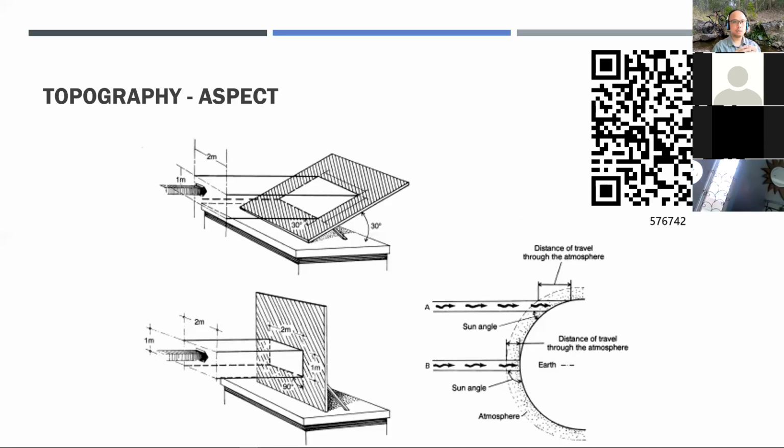As with other physical attributes, the importance of a slope's aspect depends partly on the proposed use of the site. At higher northern latitudes, for example, south-facing slopes are better suited for siting buildings that will incorporate active and/or passive solar heating. Conversely, a north-facing slope may be better suited for ski trail development in order to limit the melting of snow in late winter and early spring. That's if you have these extreme seasonal changes, of course.